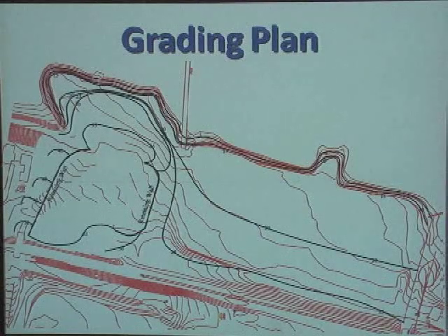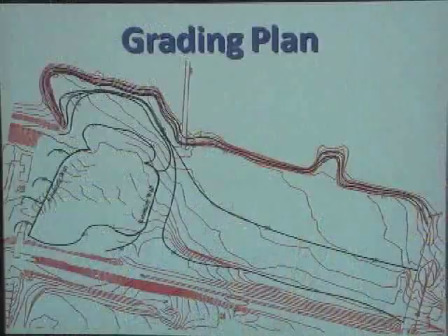There's 2 retaining walls we're going to put in, as you can see depicted. The one on the left is where the road will be following. That will be able to maintain the 8% grade as per requirements, and the other one will also let the whole complex of the restaurant and the shops get the same kind of elevation. They both need to be put up to the flood plain, so we brought that up. The basements for the restaurant and the bottom floor for the shops. The parking lot did not need to be above the floodplain, so we used it over here.